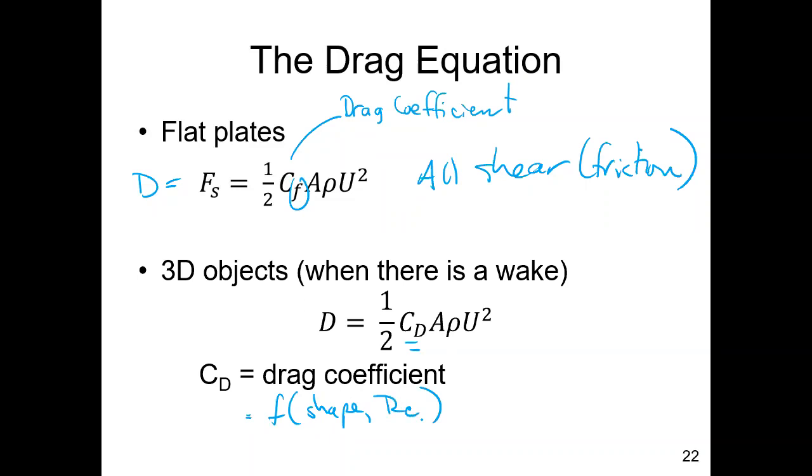and sometimes Reynolds number. And again, on your handout for today, have the handout ready for Monday, because we're going to be doing examples Monday. I'm trying not to overwhelm you with equations today because you're already stressed out. So, A is the object normal to the velocity vector. So if it's a sphere, we don't have to worry about what the size of the wake is. Everything is related to the size of the wake, et cetera, and the drag coefficient. We just mean physically the size of the object. Flagpole, submarine, train, any of these are three-dimensional.